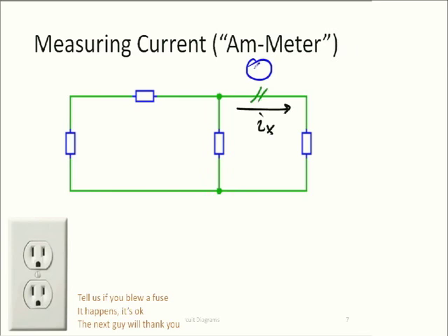Let's say this is the ammeter, which again is going to hopefully have a positive and negative sign somewhere on the box. Then we're going to connect it like this, so that the current Ix now flows through the ammeter. Okay? And then we can put it all the way around, the other way around and so on, to get a minus sign.